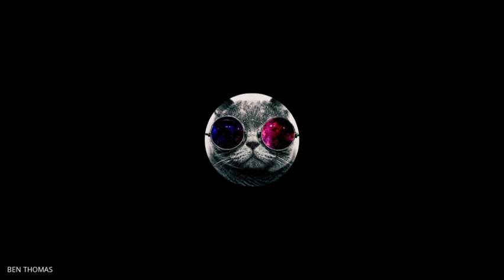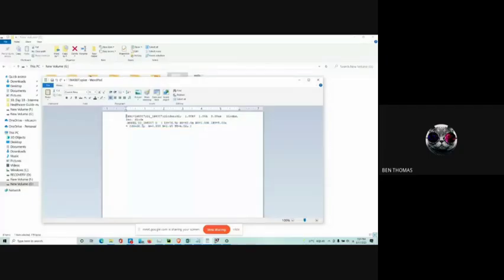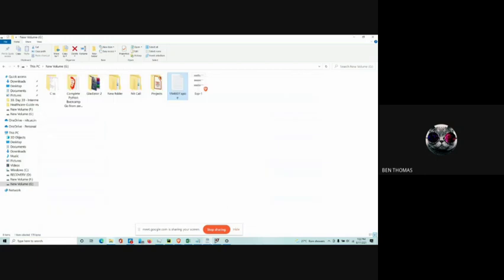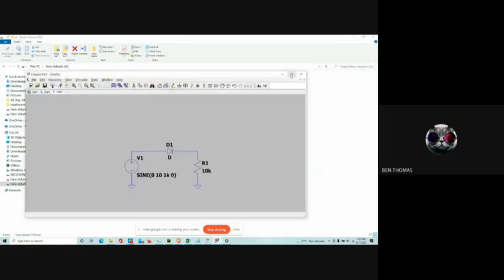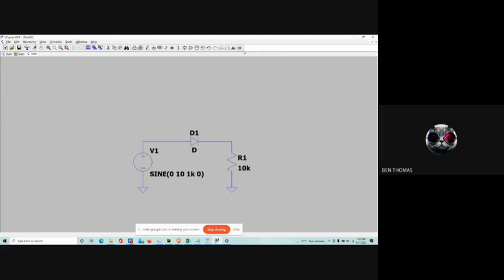You can open it with WordPad. When you open it, you can see a text, this thing right here. The first part is the source, where we got this, all those things. That's for copyright and all, so don't mind that. Copy this model up to this whole thing. You have to press Control C to copy, and then you have to go to LTSpice, and here this icon.